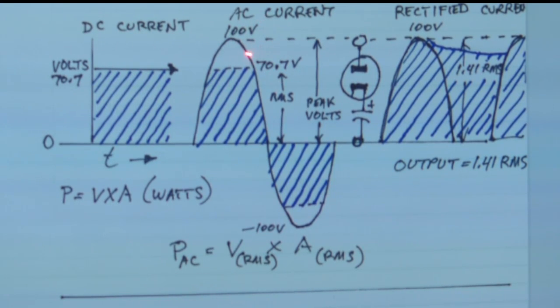Because, you know, there's all this spare space here around the waveform, and of course it goes negative. There's that spare space, and so on. And if you kind of lumped it all together, you'd probably have something like the area underneath that DC portion. So that's the story behind RMS. And of course there are other measurements. There's peak voltage here that goes from a high positive or a low negative to the 0 volt line.